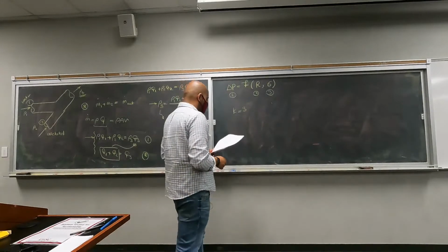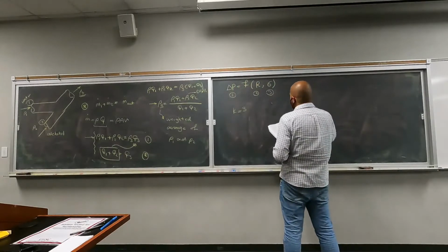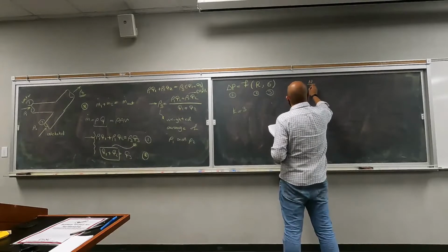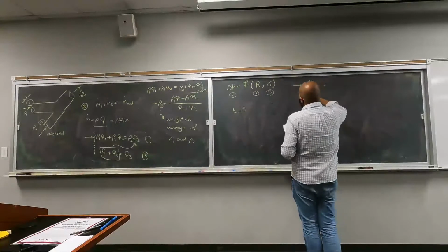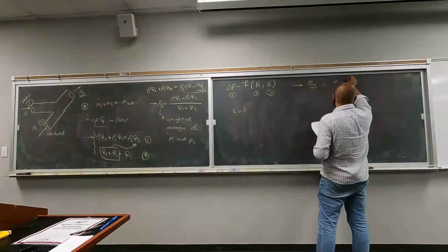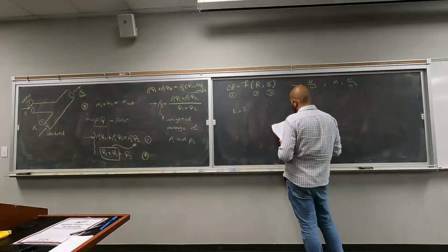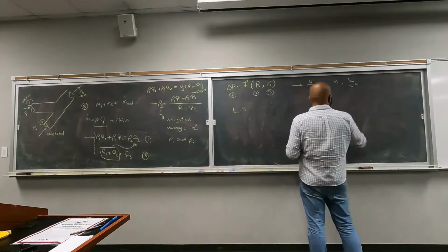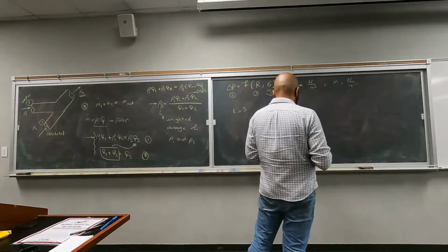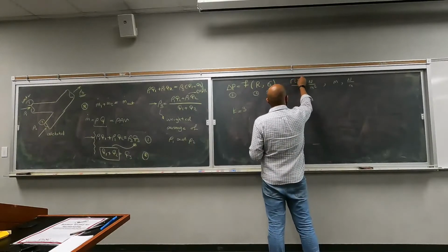Then is the number of dimensions that are present here. For delta P, we have newtons per meters squared. For R, we have meters. For surface tension, we have newtons per meter. Newtons per meter. Right? If we write it this way, this is the FLT system.